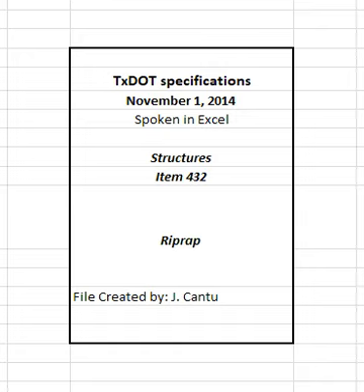3.2 Stone riprap. Provide the following types of stone riprap when shown on the plans. Dry riprap. Stone riprap with voids filled with only spalls or small stones. Grouted riprap. Type R, F, or common stone riprap with voids grouted after all the stones are in place. Mortared riprap. Type F stone riprap laid and mortared as each stone is placed.